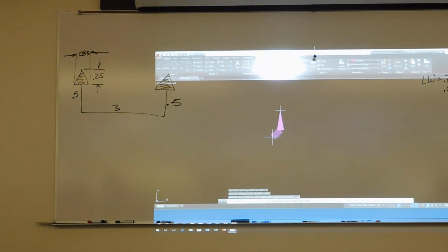Now, I can't have this width going at this. So we need to switch our width back after we make the arrowhead. So again, go into the width option. So W, enter. This time your ending and starting width are both 0. Okay, so just put 0 for starting width and 0 for ending width.